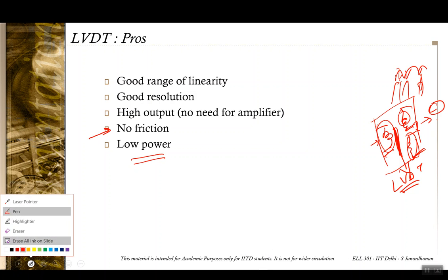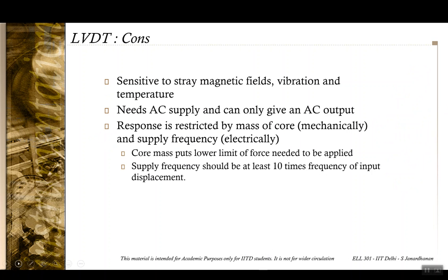But on the other hand, LVDT does have some disadvantages also. Because it basically depends upon the magnetic coupling and the transformer effect, it is susceptible to stray magnetic fields. And since we want it to be sensitive to displacement, it also becomes sensitive to vibrations and other mechanical vibrations.